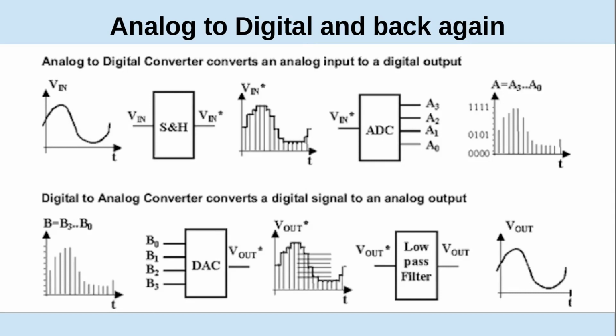Now, with a single sample, you could amplify it, or you could divide it, reduce it. But to do filtering, and normally you'll do a quadrature also. You do 2 of them, and you get one 90 degrees out of phase with the other, so you can do the processing. And we're not going to go into that kind of detail, because I don't understand all of it that much either. They use DSPs to do some of this. Yeah, and most DSPs have an analog to digital input, maybe more than one.